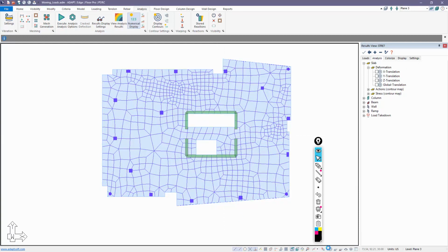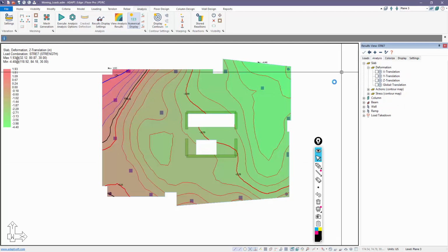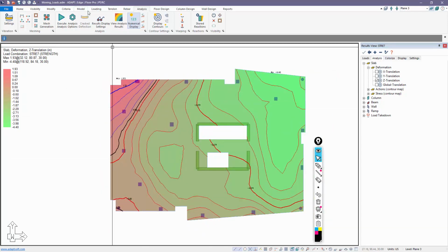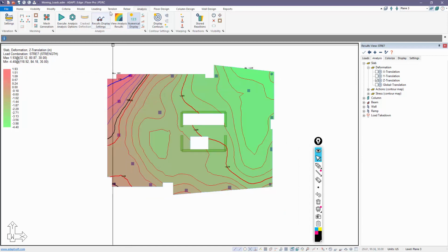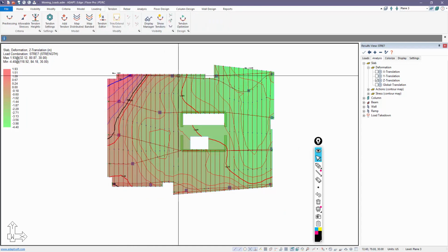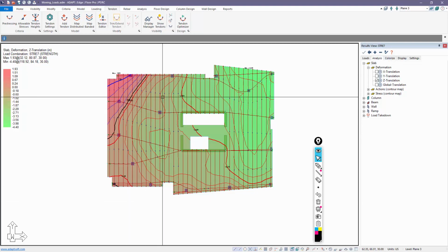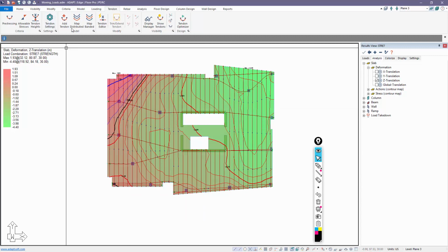Okay, back to my default display. If I look at the vertical deflection again, there's still some disconnectivity at this location. The issue is actually being caused by the tendons. This is a set of tendons, and because the strength includes the hyperstatic action for the tendons, that's solved uniquely. So we need to eliminate that from the combinations to actually produce a valid deflection result when we have post-tensioning cables considered. So we'll make this easy.